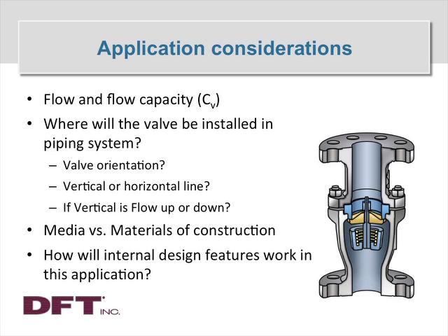And then, of course, you've got to think about the media versus the materials of construction. Will the carbon steel body with stainless steel trim work, or do I need something different? Do I need wear-resistant materials or more corrosion-resistant alloys for the body or the trim? And then thinking about what's going through the valve.